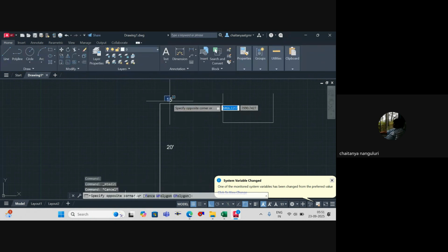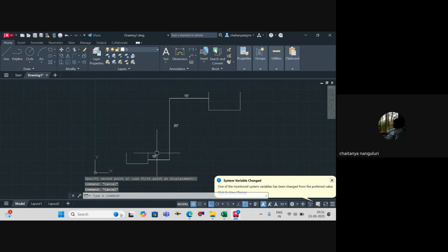If my circuit is something like this, my static head will be just against the gravity, whatever head is there. That is your static head. So in this case, what will be my static head in feet? 20 feet, obviously. So that is static head.